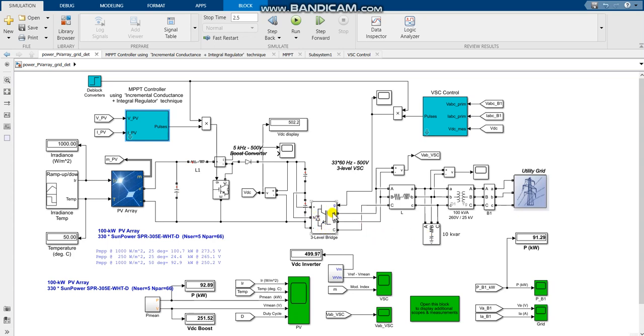Now, our 3-level bridge uses diodes and IGBTs as the semiconductor components for it. One peculiar thing about this, similar to the boost converter, is that these were programmed to have 0 volts for the voltage drop. However, realistically, there would be some kind of finite forward voltage drop as a signal is put through them. For silicon, it'd be around 0.7 volts you would see as a drop.